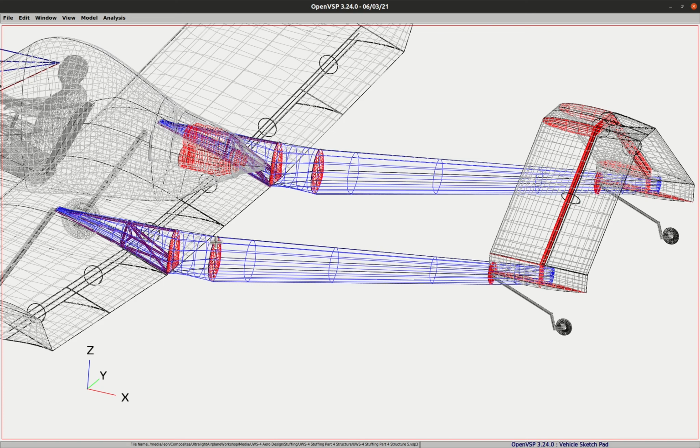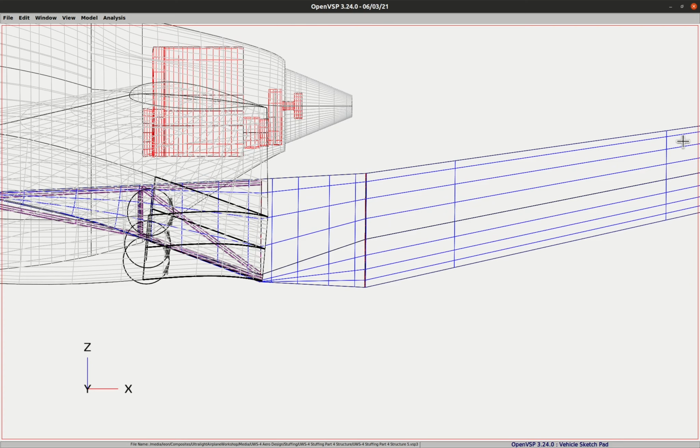And the reason I want to have a piece of bulkhead here is this piece of aluminum, this piece of aluminum have to have a place to join, and we're changing the shape from this shape here to this shape here, which is more teardrop shaped. And so we're not having a continuous straight line for these loads. There's a change in this shape here for the loads. Let's look at the side. So remember, Dan said we want to have straight line loads if we can. Well, we're not going to have a straight line load here or down here. So I want to have a bulkhead here in order to handle this kink in the load lines.